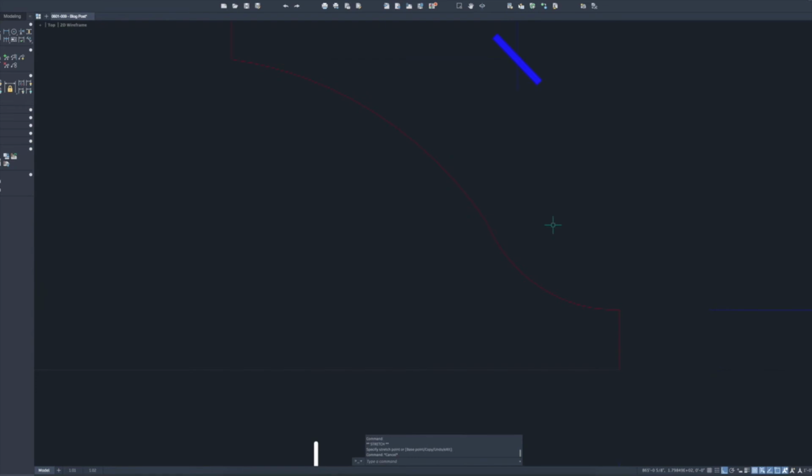Now, that would probably cause one of three things to happen. Either you would live with it, and then someone would be very angry. Some poor guy would have to sand that hump out of every single piece of molding that this cutter ever makes, or you wind up fixing it and having a cutter remade. So just keep a close eye on some of your radiuses and your transitions.